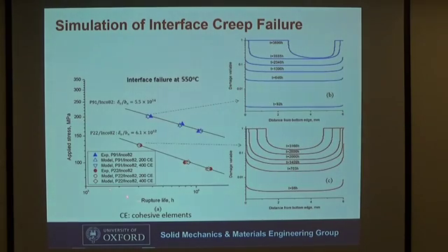So this is the final results, and the calibrated parameters of these 2. And I also have done the results using 400 cohesive elements, which you can see the 2 types of simulation give very similar results, and they are very close to the experimental data.